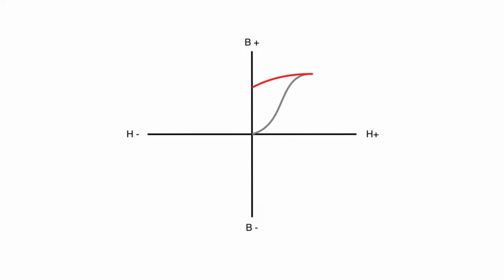As we get rid of our magnetizing force, so our magnetizing force goes back to zero, you'll notice that it retains some flux lines. This doesn't just drop out like that. What happens is there are some flux lines that retain or stay. So that might not be a good thing. You might want to get rid of those flux lines. What we call this is our point of retentivity or retention, which we're going to denote with that R.